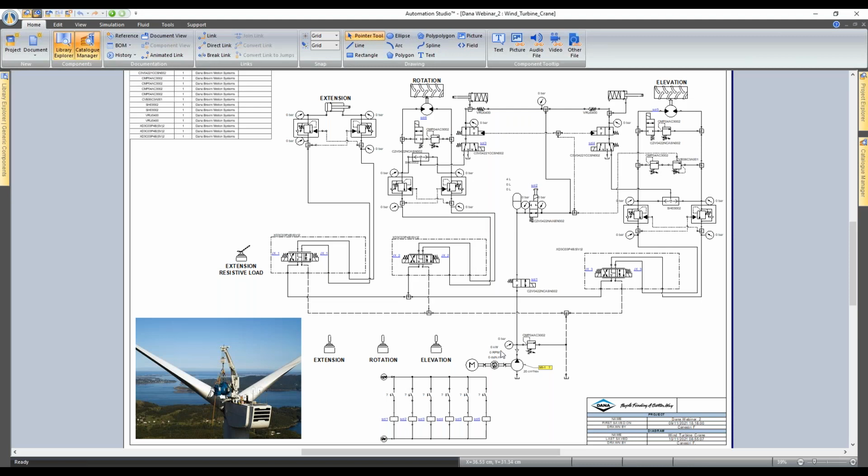As I said before, the first thing that we have to do when we start the crane is to load the pressure inside the actuator, because if the current is not available, so the electricity is not available for our system, we must be sure that all the movements, so all the working functions, such as the rotation and the elevation, can be avoided, closing the valves and being able to remove the load from our crane.